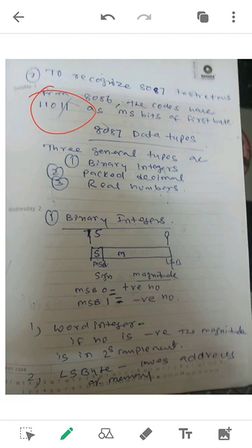Okay, so that you have to remember. For the instructions of 8086, we don't have the MS bits of this 11011. Keep in mind, for the instructions of the 8087, in the MS bits we have 11011, which distinguishes them from the instructions of 8086. We have the common queue, so in that queue we have the instructions present for both 8086 as well as 8087.